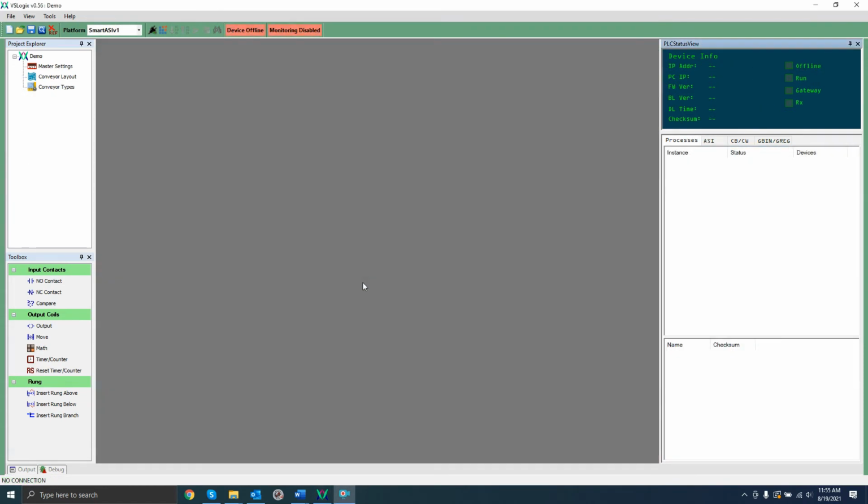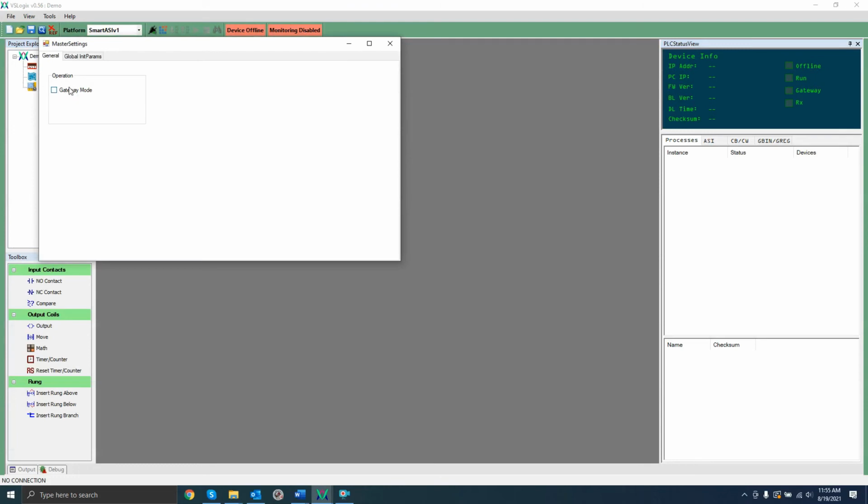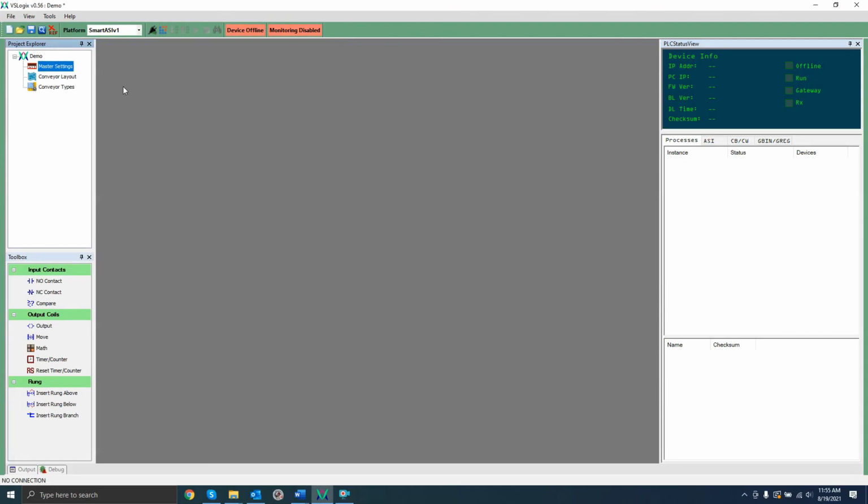The last thing I want to discuss is SmartOSI support for high-level protocols such as Ethernet IP and Modbus. The SmartOSI can operate in 2 modes, gateway mode and ladder mode. When gateway mode is enabled, the ladder logic of the SmartOSI will be turned off and will not run. Instead, the I/O of the OSI network will be controlled directly by an external master device. When ladder mode is enabled, however, the ladder logic will run and will be in control of the OSI network. In both modes, you must set up the OSI slave list to match your desired network. As usual, I recommend using the network browser for this step.